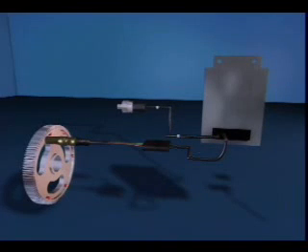The manifold absolute pressure sensor is mounted in the intake manifold after the throttle assembly. The manifold absolute pressure sensor, or MAP sensor, is a transducer that generates an input signal to the ECM proportional to the air-fuel mixture pressure in the intake manifold. The ECM uses this signal to adjust the base timing and as an input for air mass calculation. Remember, the manifold pressure after the throttle plate may be different from the turbocharger boost pressure.